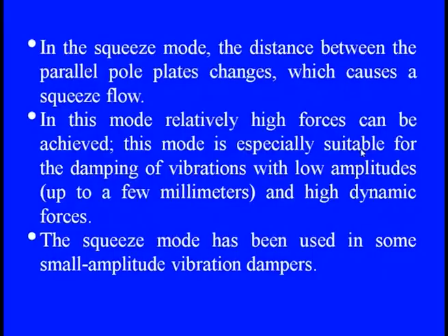And the last mode is the squeeze mode. The distance between the parallel pole plates changes, and when the distance changes, it causes a squeezing form in the magnetic particles. In this mode, relatively high forces can be achieved, because when you are squeezing, the reaction is quite strong.